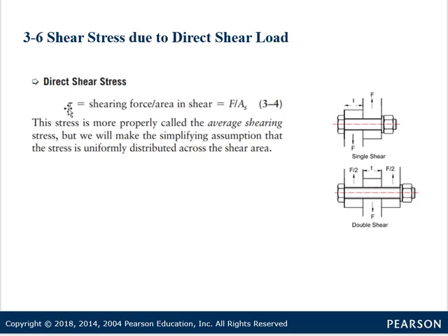Okay, so shear equals shearing force, in this case F, divided by A, which is the area that's in shear. In this case, this is one shear plane, which is the area of this fastener.